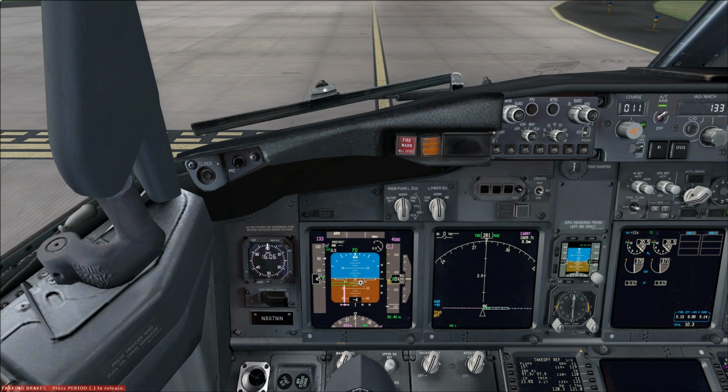If windshear is encountered near VR and the airspeed suddenly decreases, there may not be enough runway left to accelerate back to VR. So if there is insufficient runway left to stop, then you initiate a normal rotation at least 2,000 feet before the end of the runway, even if your airspeed is low. Higher than normal attitudes may be required to lift off the remaining runway, and you ensure maximum thrust is set.